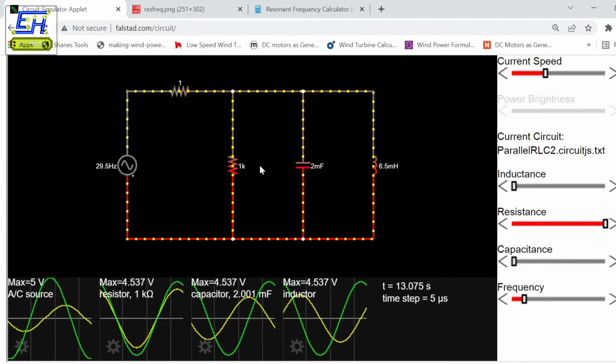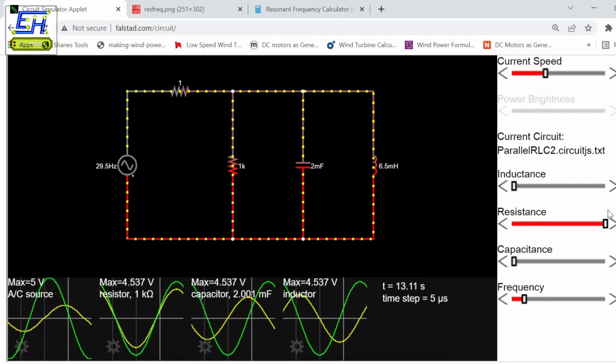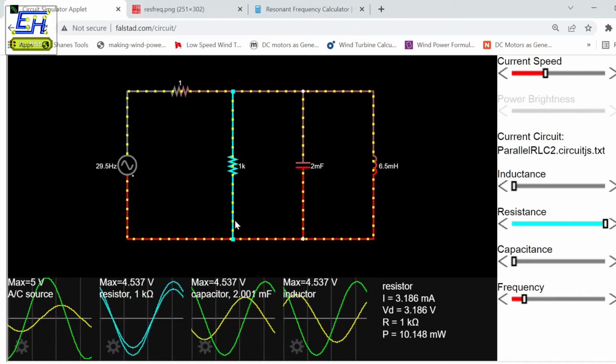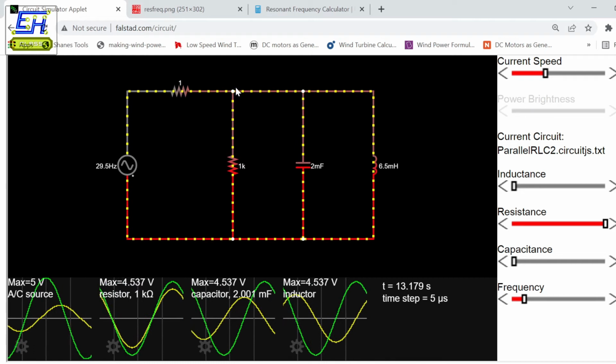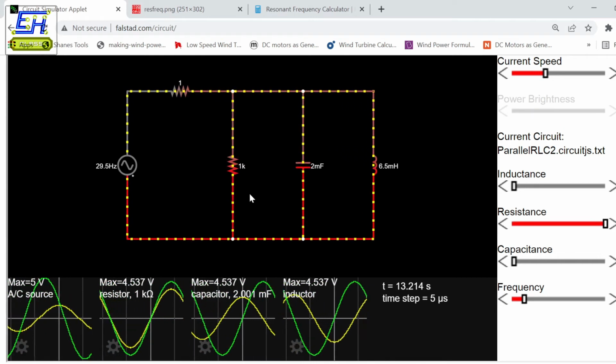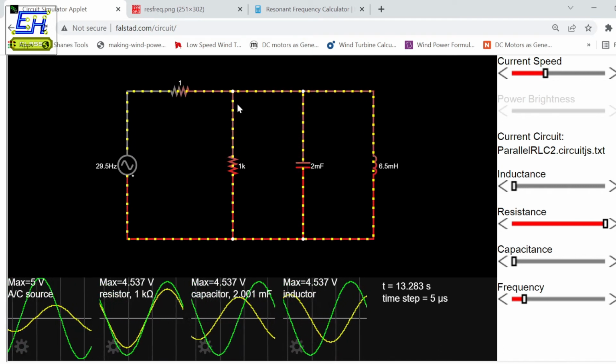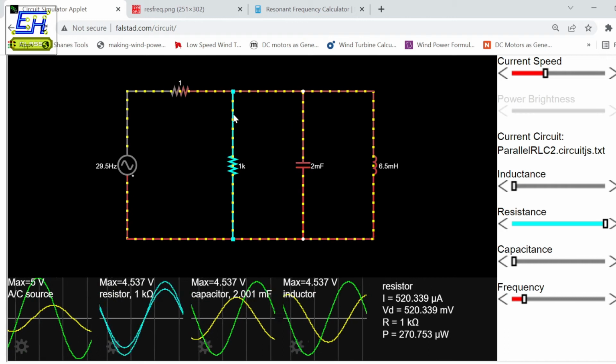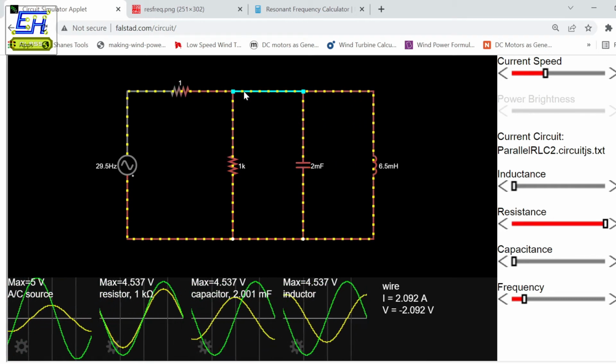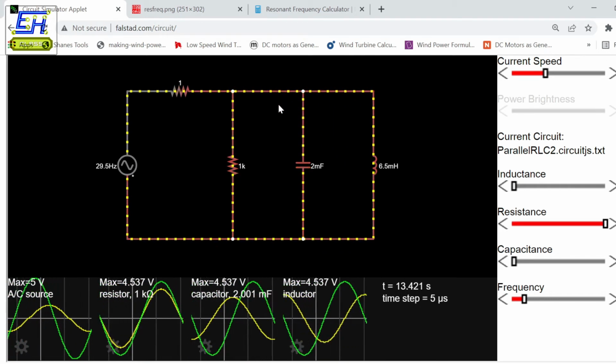Definitely, if its value is higher, it is actually acting as a shunt resistance, because it is shunting the source. If its value is higher, very little current will flow through this, because its resistance is very high. So this will cause more current to branch off here, or more current will be diverted to these elements.